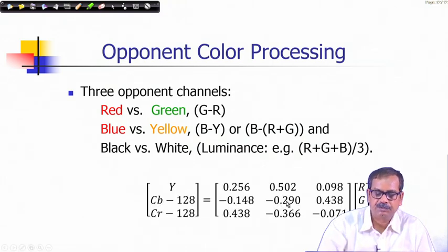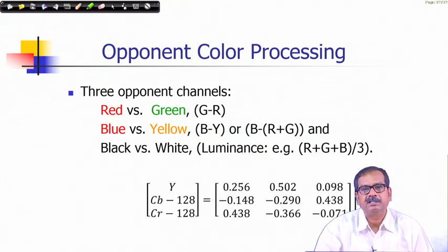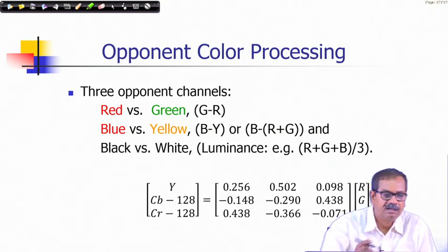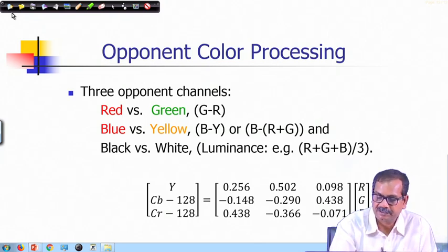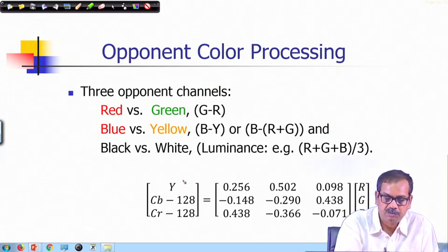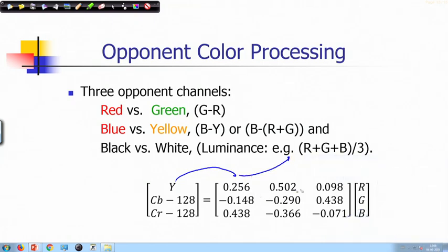If you note the YCbCr conversion, where you consider only the linear part, you will find that it somewhat follows this principle, because you can see this is red, green, blue. The Y part represents the luminance, which is the weighted average of red, green, blue, whereas the Cb, complementary blue part, represents the blue from which you subtract the addition of red and green.